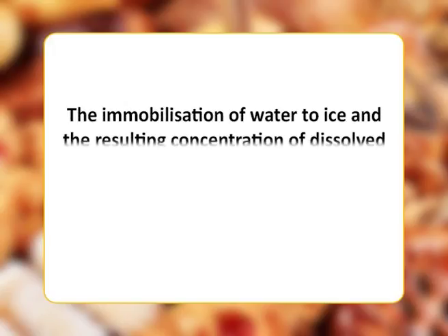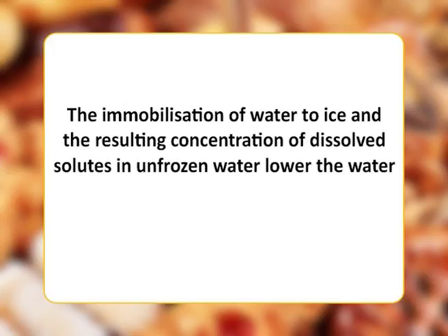Freezing. Freezing is the unit operation in which the temperature of a food is reduced below its freezing point and a proportion of the water undergoes a change in state to form ice crystals. The immobilization of water to ice and the resulting concentration of dissolved solutes in unfrozen water lower the water activity of the food. Preservation is achieved by a combination of low temperatures, reduced water activity and, in some foods, pre-treatment by blanching.